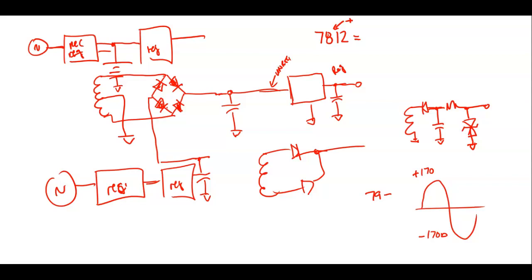Just look across your battery, crank your car, and let it run for a little. Then you turn your car off. What should the battery measure? As soon as you turn your car off, your battery should measure around 13 volts, and then overnight it'll go back to around 12. So as soon as you turn it off, it's going to measure a little high. They call it a surface charge or something like that.